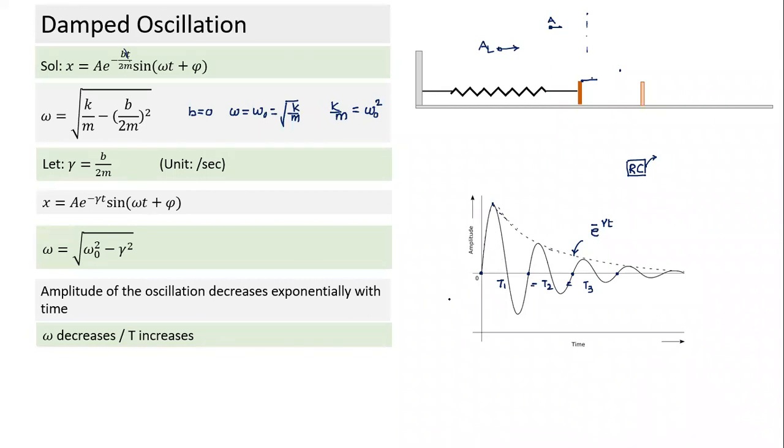Yes, Alan? So if we take frictional force as the opposing force... Just keep in mind, we are not calling it frictional force. We are calling it damping force. What is the nature of force? Force is proportional to velocity. Don't go beyond that point. It's not a frictional force. It's a damping force, which is proportional to velocity.